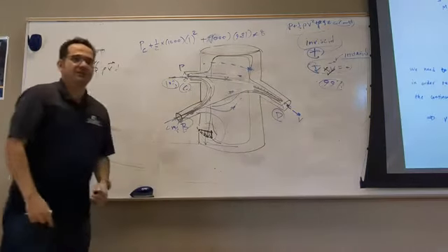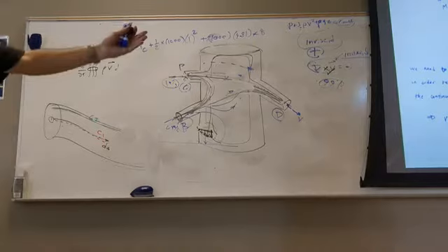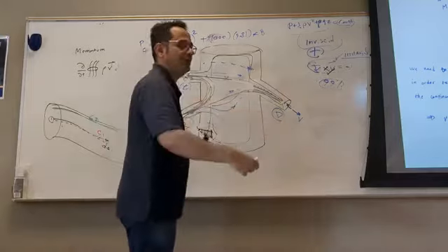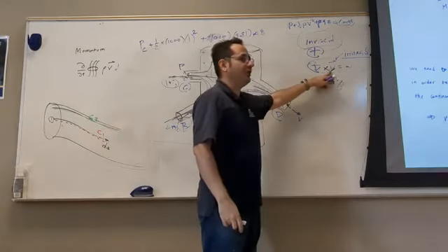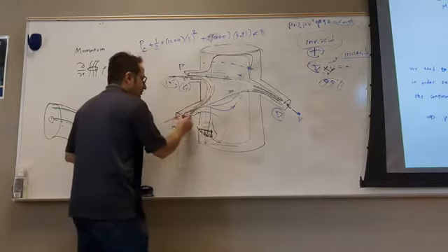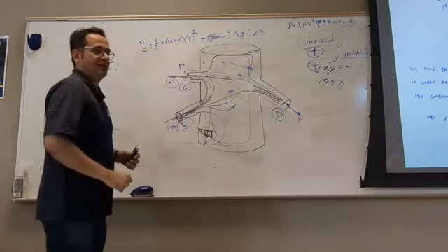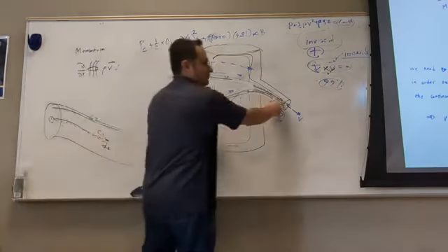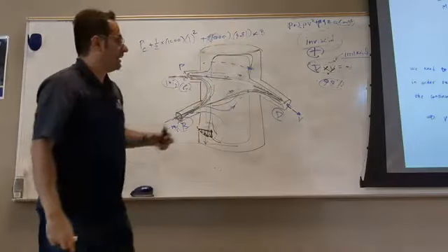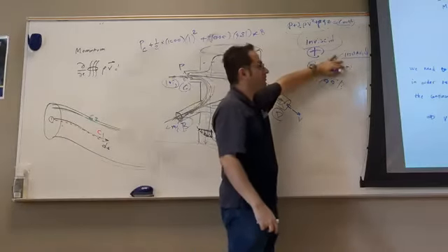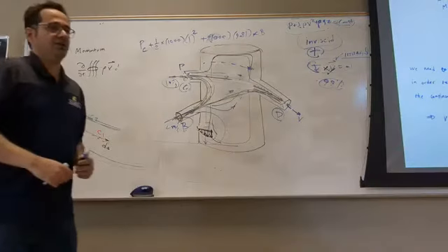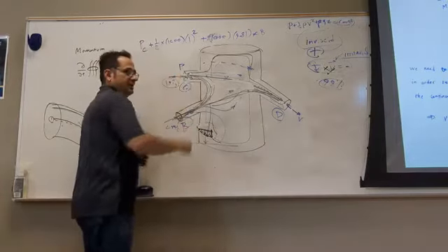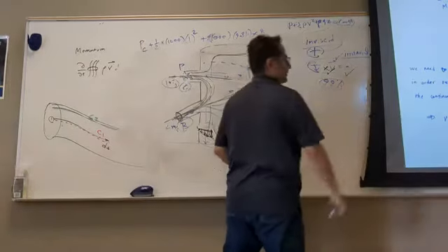Yes. So in this problem, it's irrotational, so that doesn't mean that if this is inlet, you have to start over. If you don't make this assumption, you have to start over. Why? Because you can write Bernoulli between these 2 points, and also between these 2 points, but you can't write Bernoulli between these two. So if you don't have the assumption, these equations are not consistent. That's the reason when I'm writing Bernoulli between these 2 points, even though this is outlet, I'm also making this assumption of irrotationality.